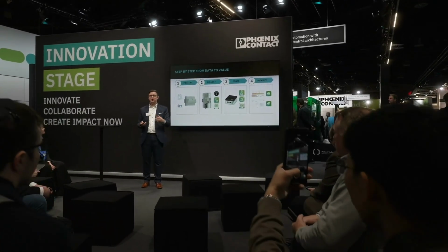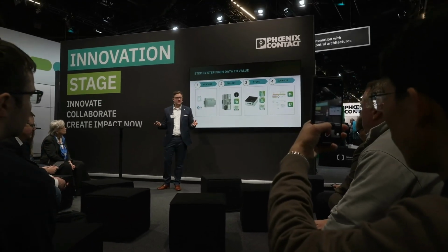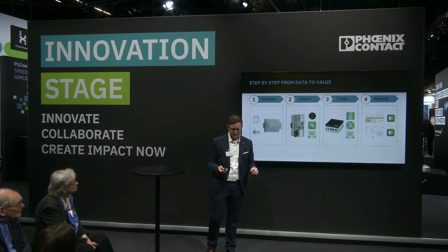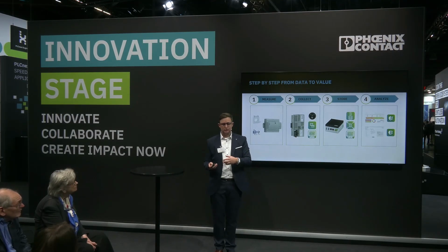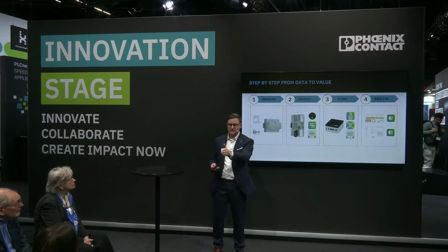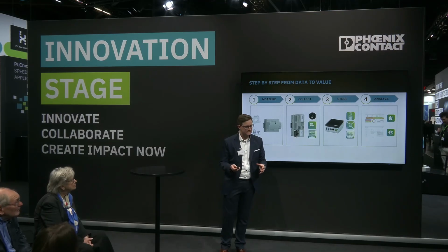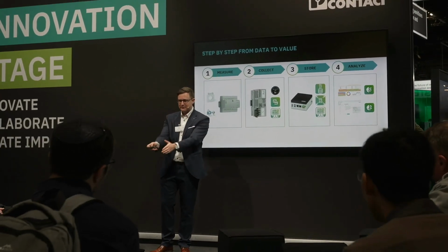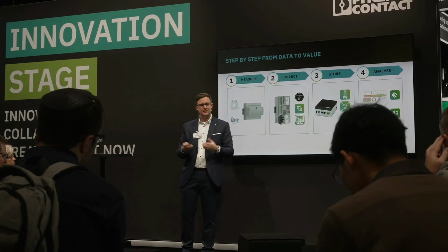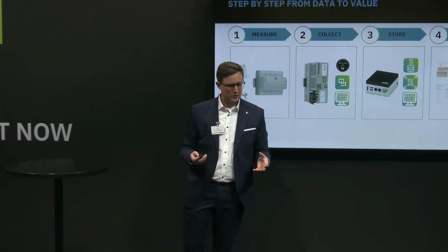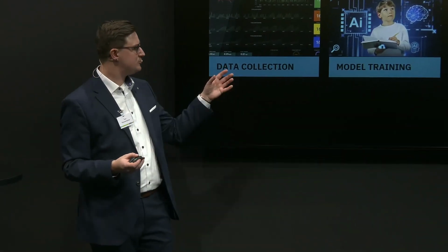And that's why we know that for OT, it's not about time synchronization on second level, it is about time synchronization on milliseconds level. Because if I have a machine and I want to use vibration sensors, an energy meter and temperature sensors, I need to synchronize the data points in order to form a time series. And it's the same in our daily life. If I want to improve something, I really need to know every step in my optimization in the frequency that I need to visualize this, that I need to analyze it further. So that is really a key for us to come to analysis.